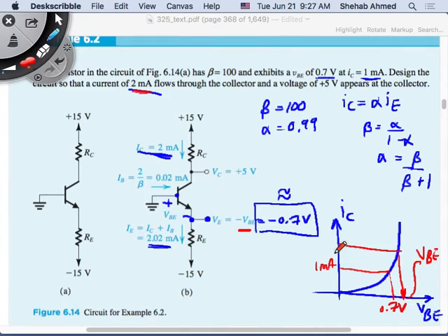So then we do this ratio, right? Remember, we have I at operating point 1 is equal to the saturation current times e to the VBE over VT. We get I1 and I2, do the ratio, take the natural log, and then we will find the VBE.